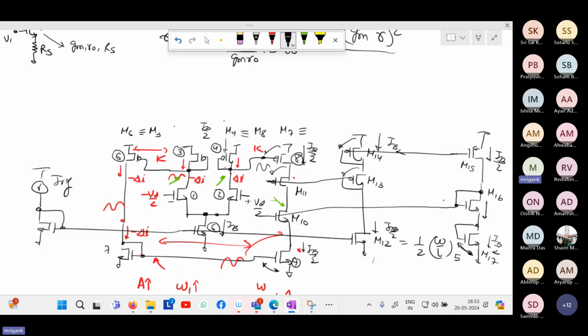So this will bias the output stage. And then here you have the high impedance node. You can operate it as a high gain amplifier, which is basically self-compensated. So this is another way of improving overall gain in this topology and getting gm ro whole square gain. In this case, as I told you, why do I like this topology more? Because the compensation is slightly easier.